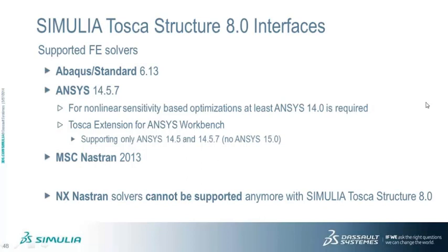So far we do not support ANSYS 15 with our ANSYS extension, so please make sure that you have the correct ANSYS versions if you plan to use ANSYS Workbench together with Tosca. On the other hand, we're supporting MSC Nastran up to version 2013. And at this point, since Tosca Structure 8.0, we're not able to support any more NX Nastran solvers. This support has been stopped with Tosca Structure 8.0.